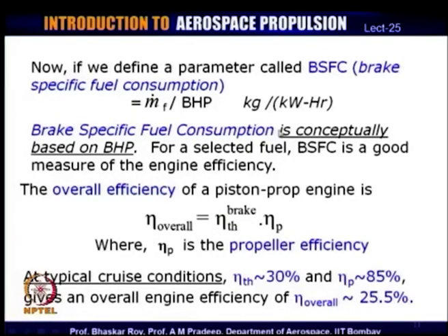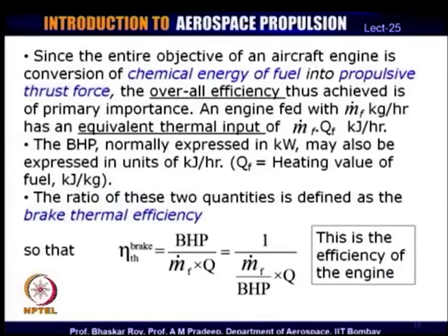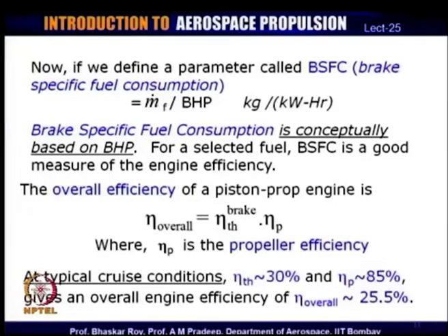Now, in most of the modern engines, BSFC is quoted as the figure of merit for the engine efficiency. We have just defined the engine efficiency or brake thermal efficiency, but most engineers prefer to use BSFC as a measure of the engine efficiency.